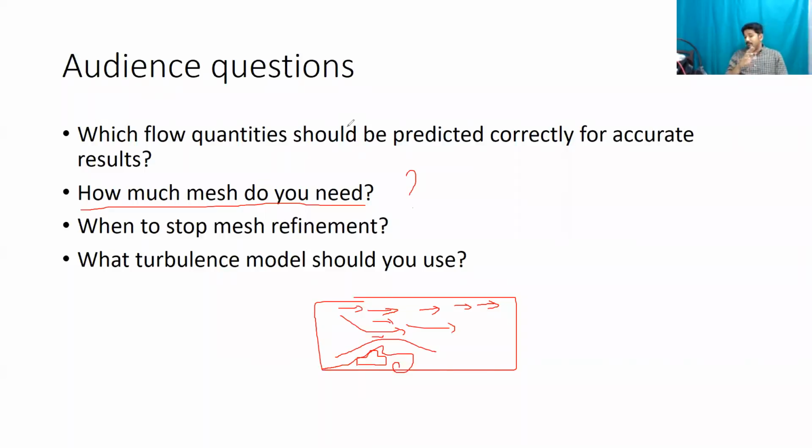Anirudh, 1 mm. Yes, that might be considered as fine mesh in certain cases, but for aerodynamic simulations, that is really, really large. 1 mm is really, really large. So the thing that you guys need to focus on is how do you quantify this? And there is a parameter called as your y plus. Okay. Yes. Well, based on the law of the wall, sure, why not?